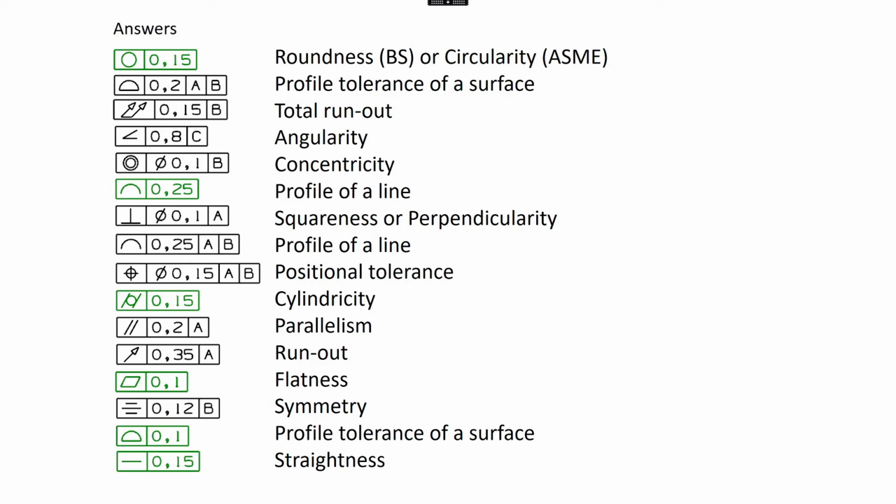On a face, it can actually do flatness. It can tell you if the face is dished in one direction or another. So total runout is doing a lot of things for you. It's a very good way of making sure the part is correct. It sort of tells you a little bit about an envelope, because you're guiding the DTI across the surface at one setting.